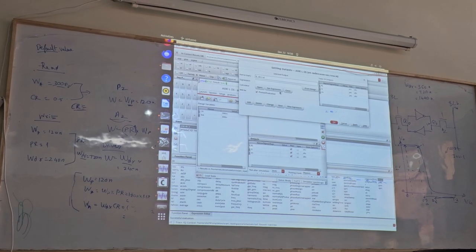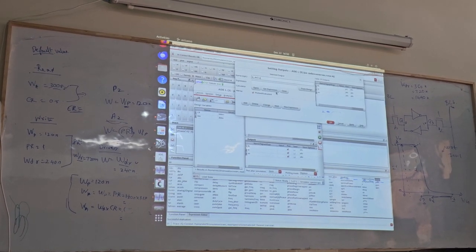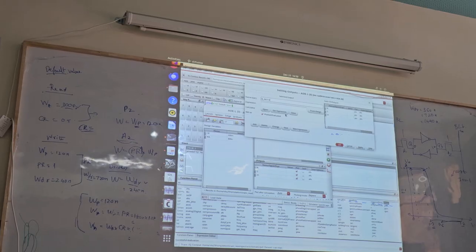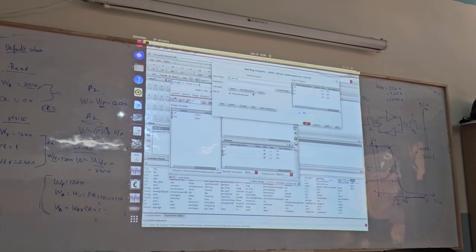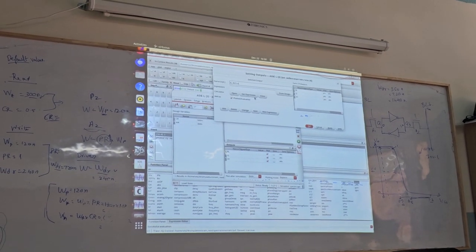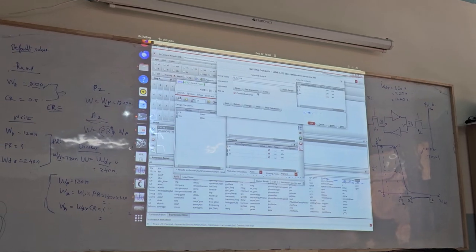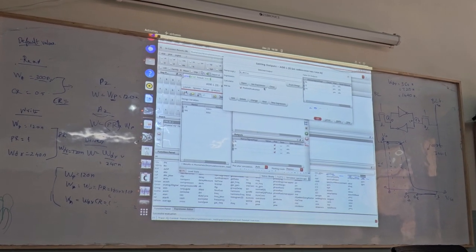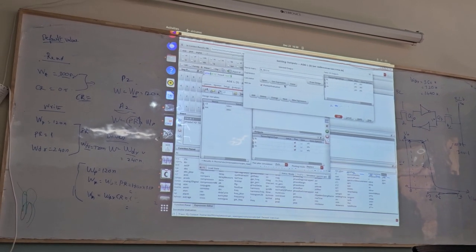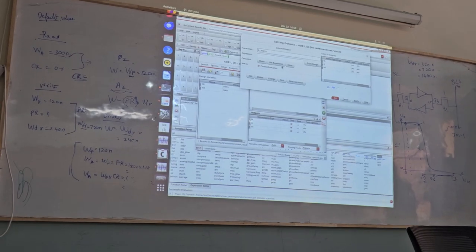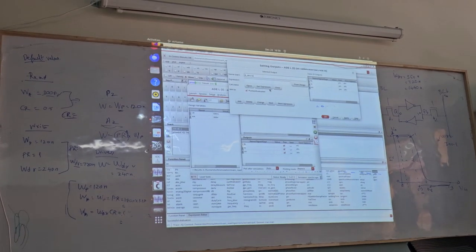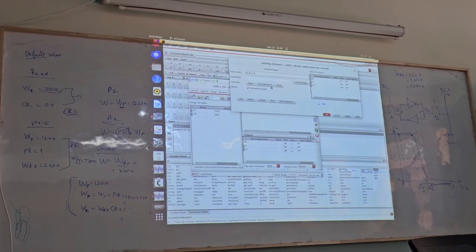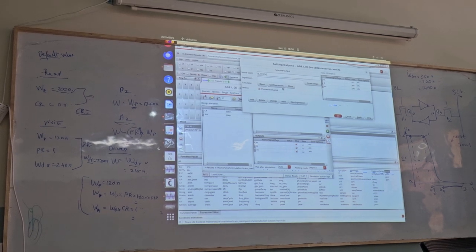If it is a constant value like a VDD, when you have a supply voltage, then you can expect to be closer to 0.6. But then because the voltage is being stored across the capacitor, it starts losing. The moment it is trying to rise up, it is also losing its charge, due to which the voltage across the capacitor keeps dropping, and the maximum rise is not close to 0.6.